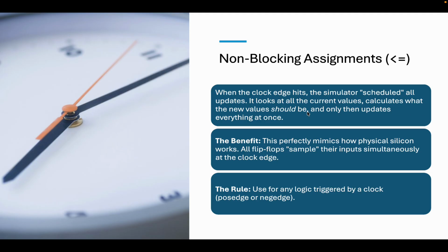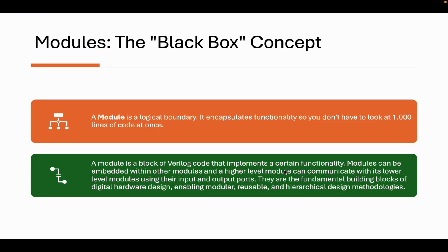It calculates what the new value should be and only then updates everything at once. This perfectly mimics how physical silicon works. All flip-flops sample their input simultaneously at the clock edge. That is the rule used for any logic triggered by a clock. If you are using a positive edge or negative edge, you can use a non-blocking assignment.